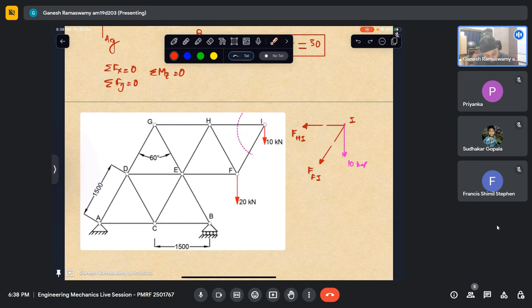So if we have marked this as from here at this cut, if we have marked it like this, it implies at this end it will be like that. If both are pointing in the same direction, it will have rigid body motion. It is undergoing tension or compression only when I push the right side this way and then I stop it. Then the member is getting tension or compression, depending on what I am applying. So whatever I apply here at the opposite end of the member, I should apply the opposite way. I hope that is clear.